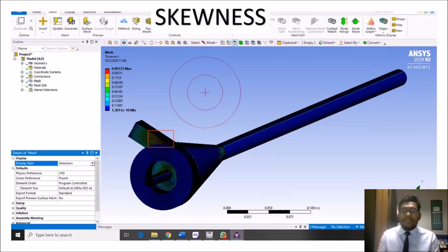Next is skewness. The rule of thumb of skewness is that the skewness value should be below 0.7 for good skewness, and we are able to achieve that. About 90% of our design we are able to achieve a good skewness. There are some parts which are above 0.7, up to 0.99, because of the complexity of the part as well.